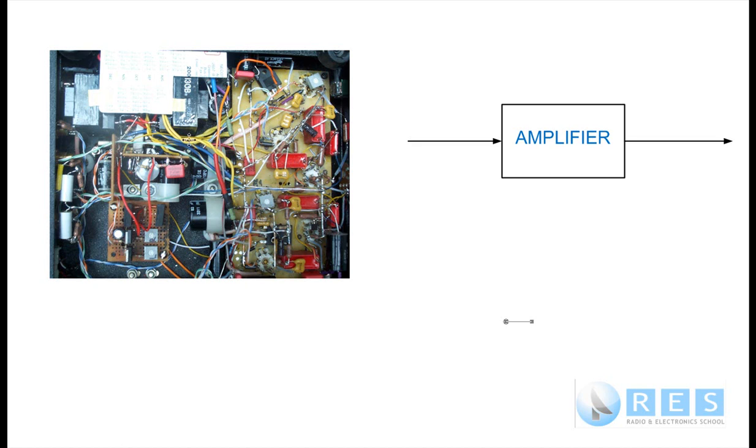Maybe the stray parasitic circuit is in this part of the wiring loom here. So if we just pulled that around, adjusted it, we will change its resonant frequency, and that could stop the parasitic oscillation.